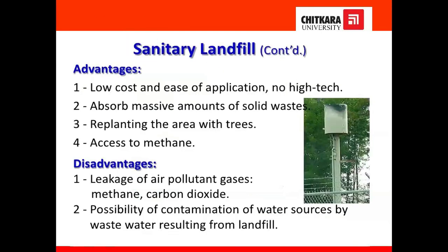What are the advantages and disadvantages of the sanitary landfill site? It is low cost, easy to apply, and it can hold massive amounts as compared to the open dump site. The area can be replanted, as we have already discussed. Trees can be planted after covering with soil. Then it can generate methane, which can be used as energy.